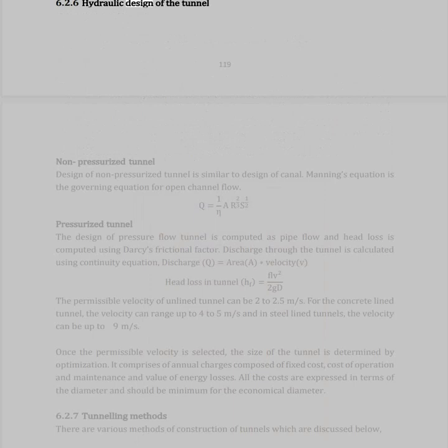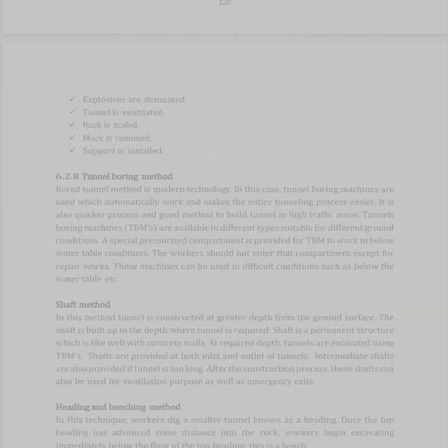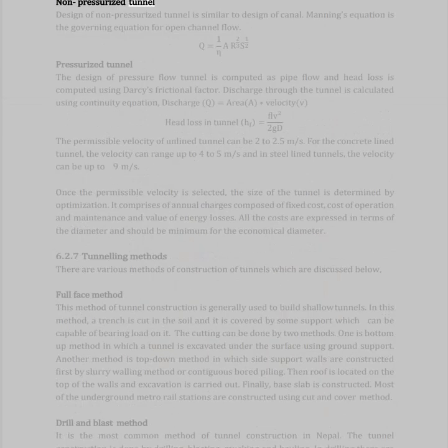6.2.6 Hydraulic design of the tunnel. Non-pressurized tunnel. Design of non-pressurized tunnel is similar to design of canal. Manning's equation is the governing equation for open channel flow. Q equals 1/n A R^(2/3) S^(1/2).